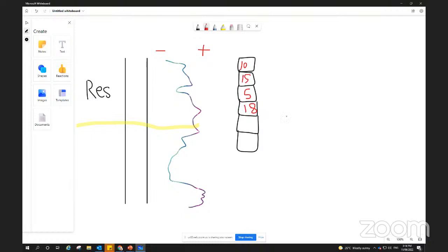So you end up with a grid that matches the input data. If it's not matching the input data, then there's a problem, so you need to scale up the cells again and make them smaller. That's why I say again that a fine grid is preferred to capture heterogeneity. You can try it in Petrel or any other software, RMS, or even in an Excel sheet, by the way. The smaller the cell size, the better the capture of reservoir heterogeneity and porosity and other properties' behavior.